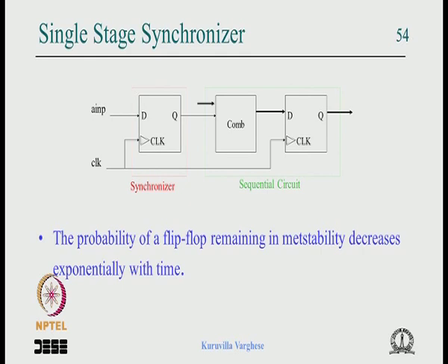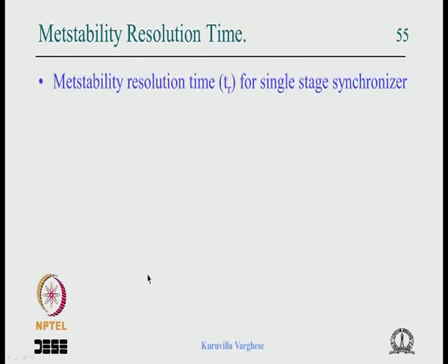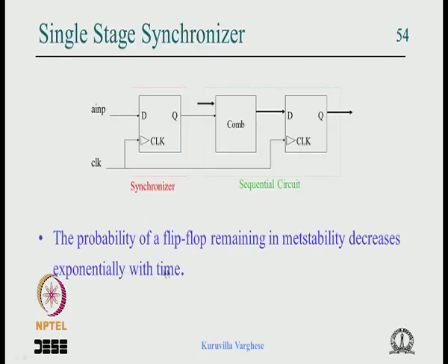So what is the time available for the flip flop to resolve? That time is called the metastability resolution time. That is the time available for this output to resolve, to come out of metastability, okay.